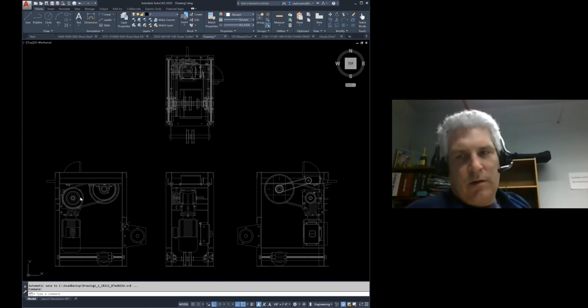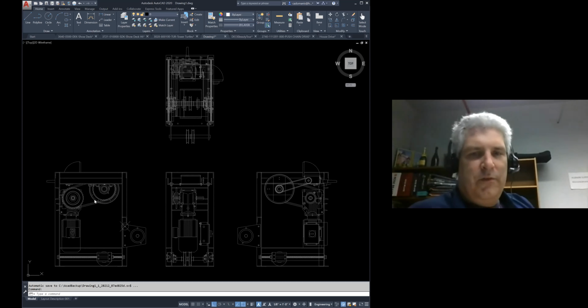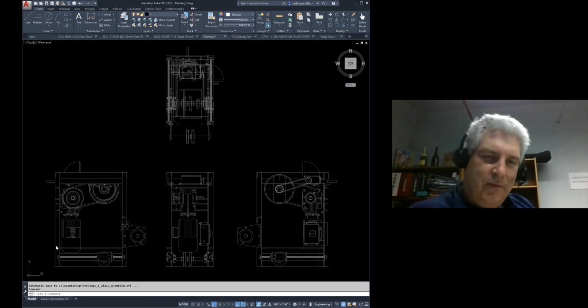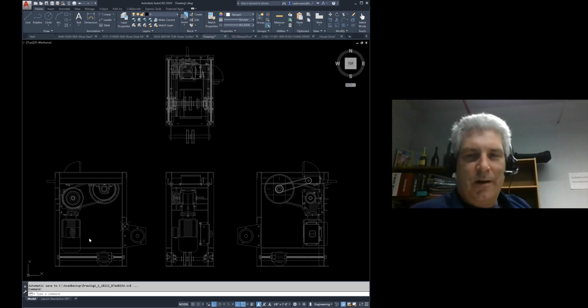And historically, I'd say the rationale there was that if you looked at failure possibilities, it was all the stuff upstream of this machine, the electronics, the controls, the PCs operating them, that were the things that everybody was worried about failing. And so there was always a desire to be able to quickly disconnect the load, i.e. the drum and the cable and the pallet it was connected to, from this motor package, so that you could put a crank on the end of that shaft and move it mechanically the old-fashioned way.